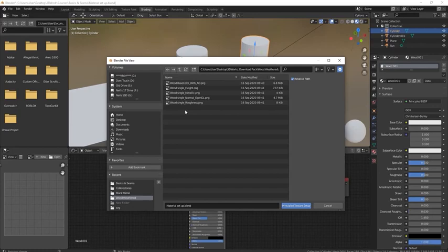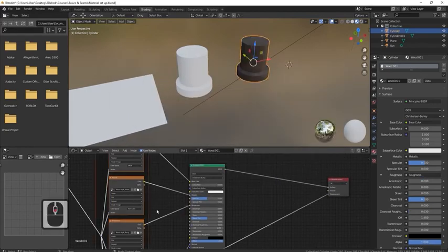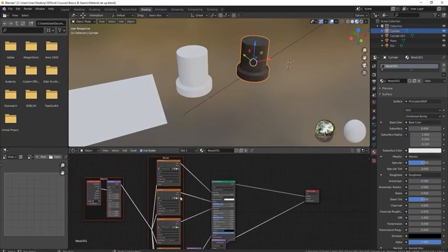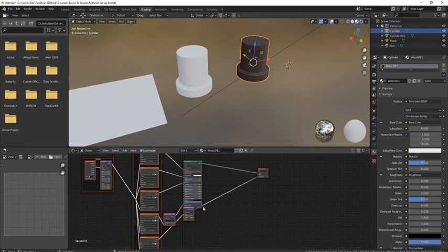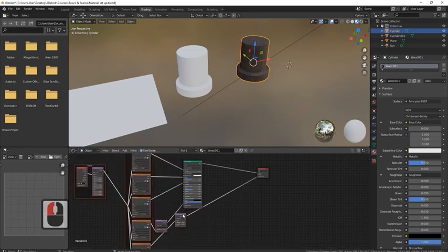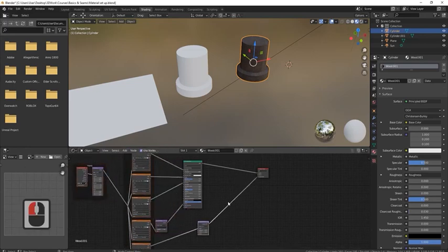They're normally the basic 5 maps. So now what we need to do is come to the first one and shift select the bottom one, and then that'll select them all. Then come over to where it says Principled Texture Setup and click that on. And there you go, they've all come in. You'll notice Blender has automatically set everything up for us, and this is part of what the Node Wrangler does.